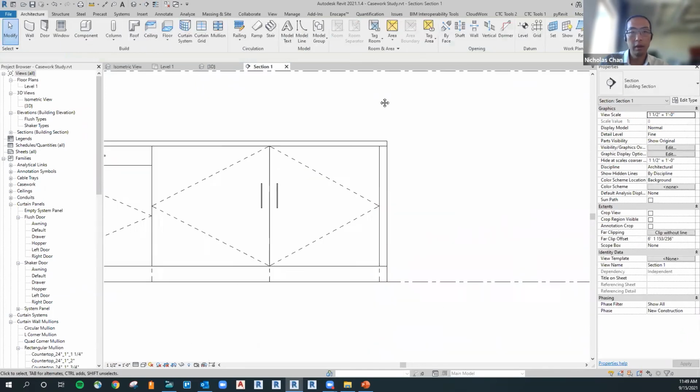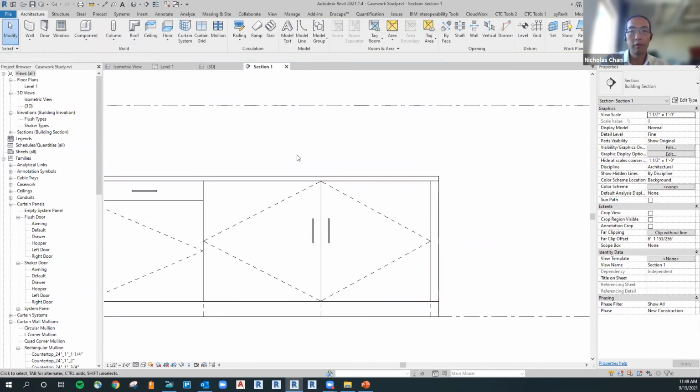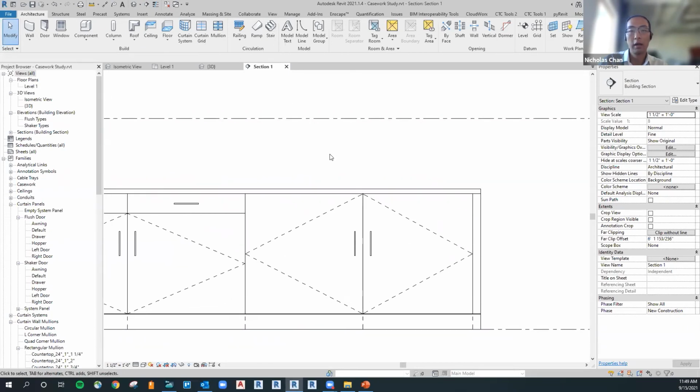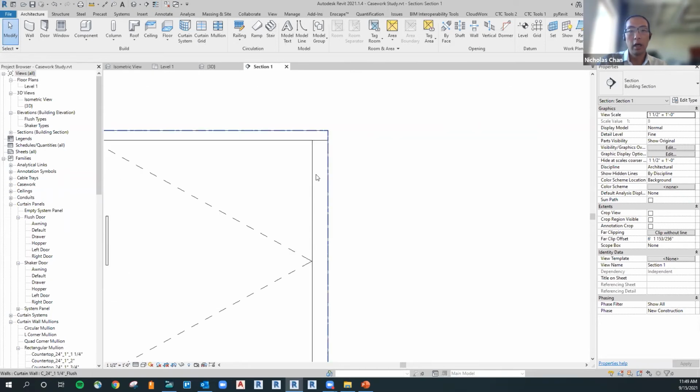You can modify that to increase it to show more. If you want to do something like a half overlay or something that really does expose a filler panel or the cabinetry behind a cabinet door, then I think where Matt was just about to go, you can use rectangular mullions to approximate that. To show, say, maybe there's a 1-inch gap between these cabinetry doors.